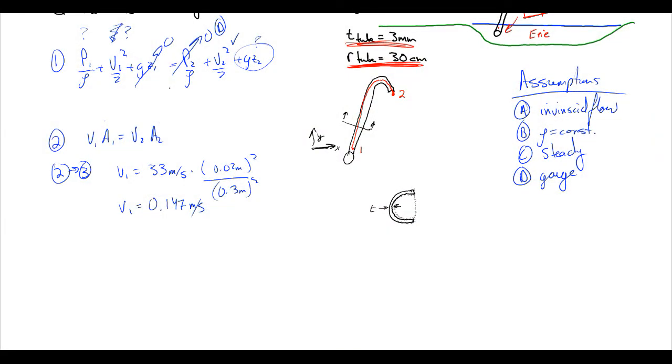If we draw a volume all the way around it, what we see is that we have a pressure force from inside of the water that's pushing in this direction on the control volume. That's what we have. It's called a control volume. But we'll go into much more depth about that in chapter 5. And then also acting on this cutaway is a tension within the pipe that's pulling in this direction. And that's it. That's the only things that are acting horizontally on this pipe are pressure from the inside pushing the thing out, and then tension within the pipe holding it together.